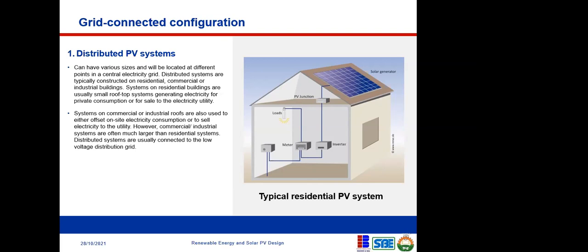For some of us here who are already very familiar with the power systems in Nigeria, of course, you will know that we have the 330 kV line network. From there, we have the 132 kV transmission network. They will now come down to the 33 kV distribution network. So if you're doing it at a commercial level, in most cases, you're feeding into the 33 kV distribution network for further distribution to wherever it is needed, where it will be stepped down further to 11 kV, and then the 415, 400, not 415, and all of that.